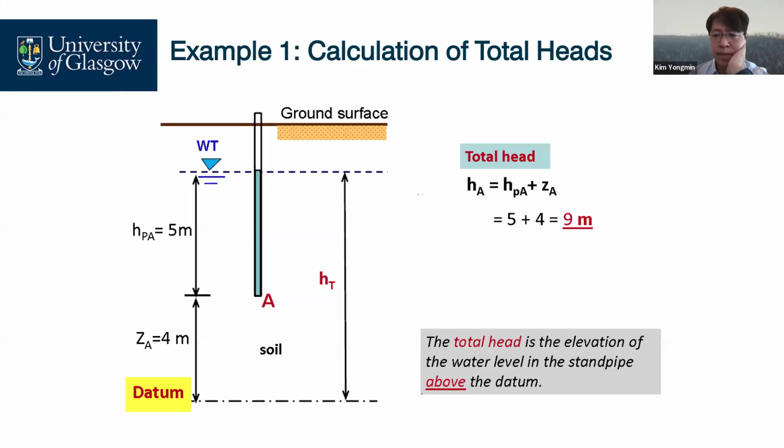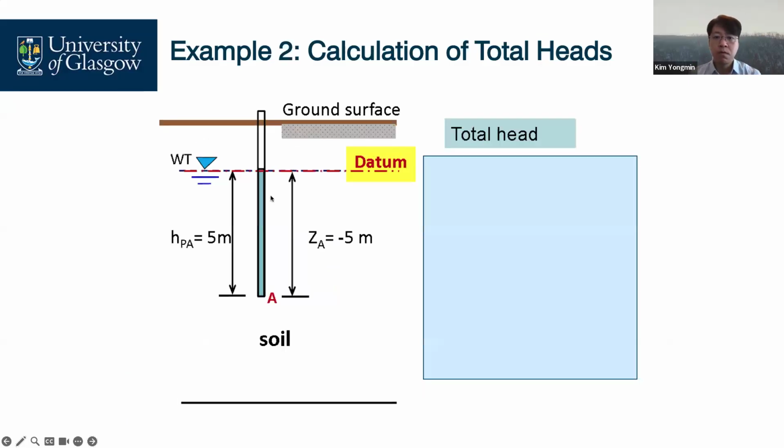Hi, Prof. I remember that you mentioned we can assume our datum on our own. Yes, you can move it here, here. What about this condition, where our datum was relocated here? Recalculate the total head at point A. Total head equals pressure head plus elevation head.